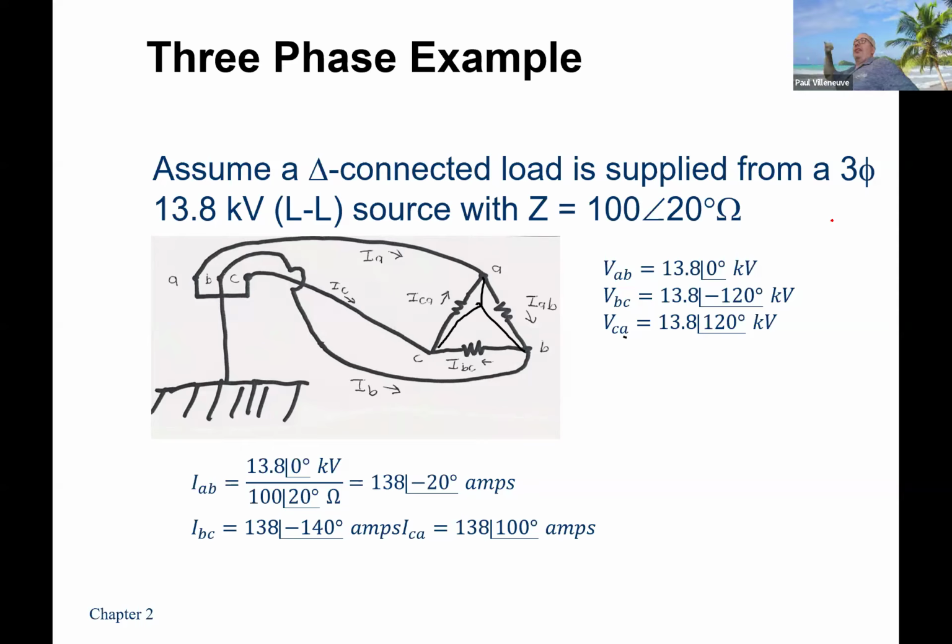And that's because if I tell you the line voltage, that's usually going to be the highest voltage. So if I'm going to go work in a substation, I want to know what the highest voltage I'm going to be prospectively seeing because I don't want to get zapped. I don't want to buy equipment that's rated for 50 kV when I could be seeing 85 kV. So when you walk into Orrington, you see it's 345 kV. That's 345 kV nominal line voltage. The actual voltage is a little bit higher, like 352, 353. But the nominal line voltage is 345 kV.